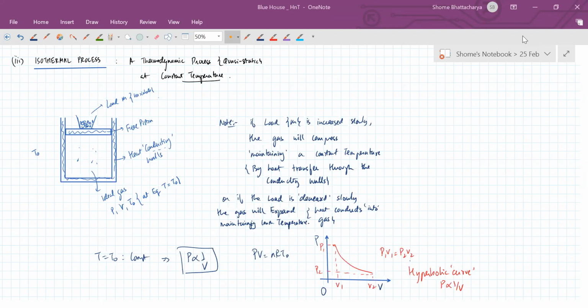Yeah, for one step processes, we cannot draw a graph like this because there is no intermediate state between initial state and final state. And therefore, our equation for work done, the integration of P dV, will not be correct, because we cannot predict the curve through which the process happens.